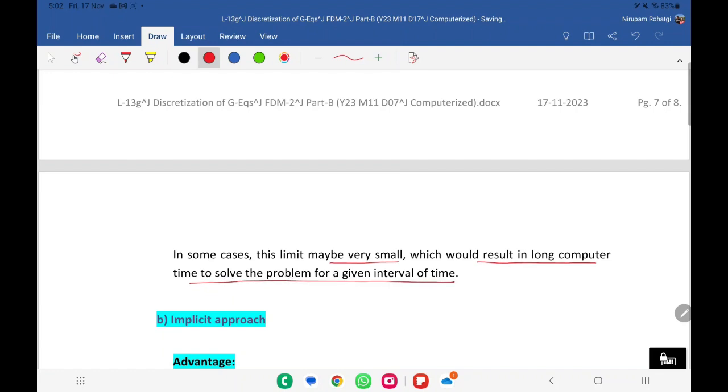Even when it is an explicit approach, because you want the solution procedure to be stable, you have to reduce the time steps so much that the calculation in the explicit mode will come out to be taking more time than the implicit approach. Are you getting the point? While solving each step is very quick in explicit, the number of steps increases so much that it becomes uneconomical from the calculation point of view.